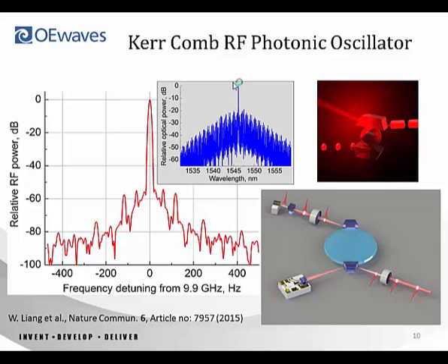And we have an evanescent prism coupler. So at the next session, you'll see first results where we achieved good coupling with planar waveguides that would allow integration of these resonators much more efficiently into optical platforms. And this kind of structure can be very small. You can see that the laser by itself is a couple of millimeters in size, and the resonators usually don't exceed 5 millimeters in diameter and 100 microns thickness. And the whole structure can be packaged pretty tight. And power consumption is usually very small, since in our conventional devices that generate spectrally pure RF signals, power from the laser is less than 10 milliwatts.